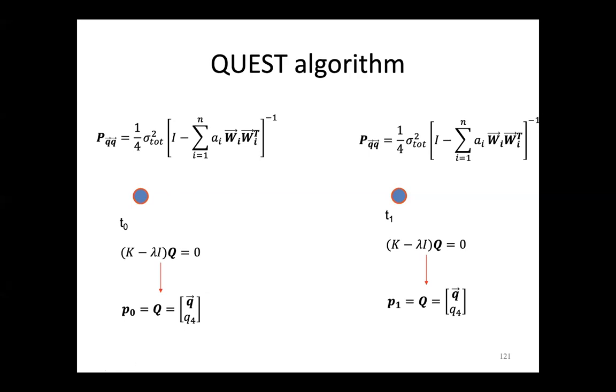So we already identified the stars, and we're trying to use the sensor to determine the attitude at that initial state. For the Quest algorithm, we have seen that the problem is only an eigenvalue, eigenvector problem. So we have to solve this equation by using the characteristic equation for the Quest algorithm, and we are going to determine the quaternion Q.